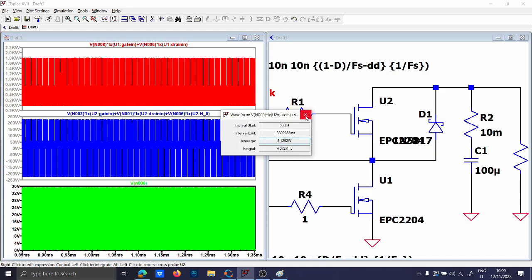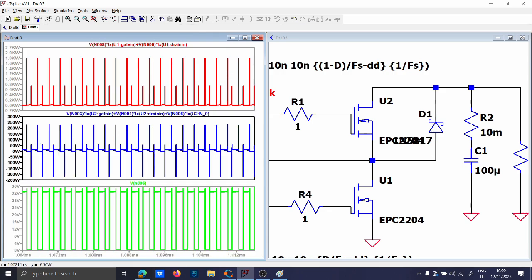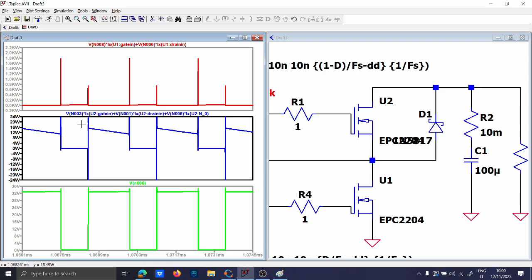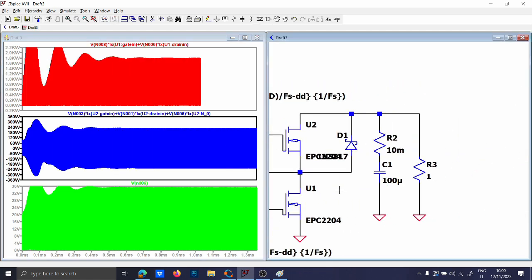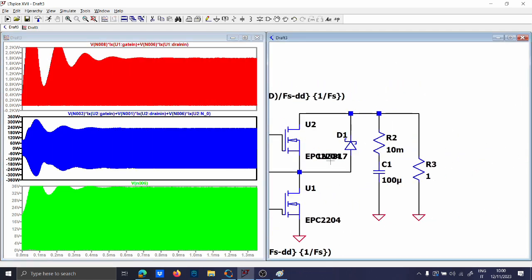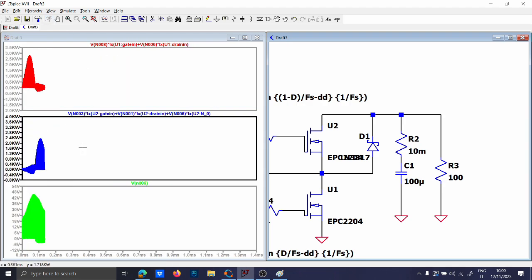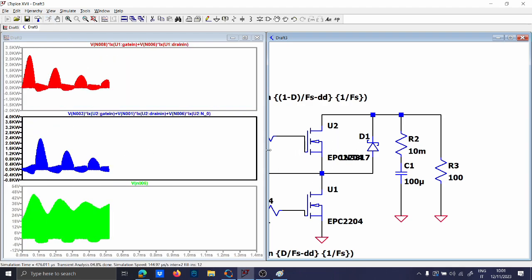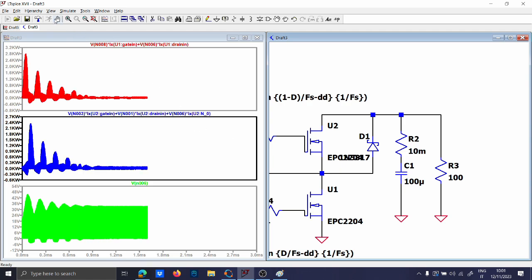We have 8.102 watts. This is because we are in high load condition, and as you can see here, it's not that high of a switching loss condition. It is more conduction losses. If you zoom, you see that there are more conduction losses than ever. And so it is because we are in high load, and the conduction losses are prevailing over the switching losses. But if I put a light load, you will see that the high side has not so much losses, because it is not switching. This guy is not switching, so it has a negligible switching loss.